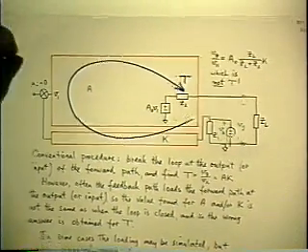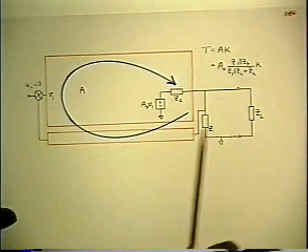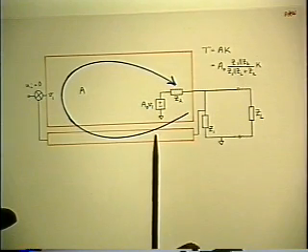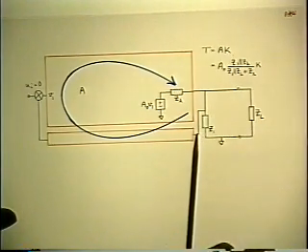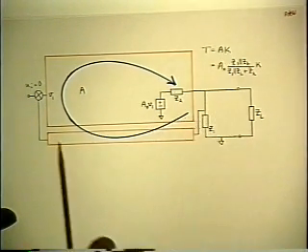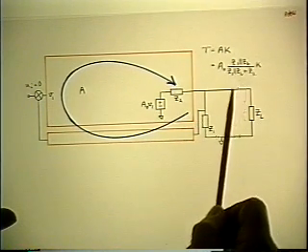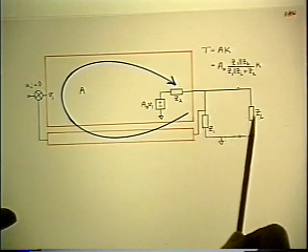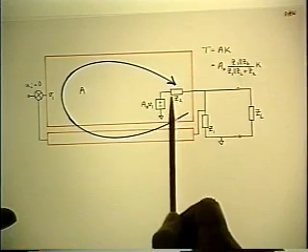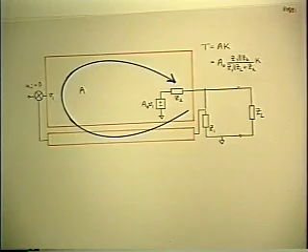Now, in the original configuration, the loop gain is the product of the gains of these two stages, which in the block diagram you can identify pretty easily. T is A times K. Starting from this point, you go through the K box, then you activate this generator with A0, and then you find the voltage back at this point again by using this impedance divider, which is Z1 parallel ZL over the same thing plus Z2. That's the correct answer for the loop gain.